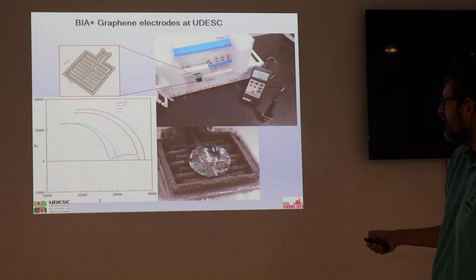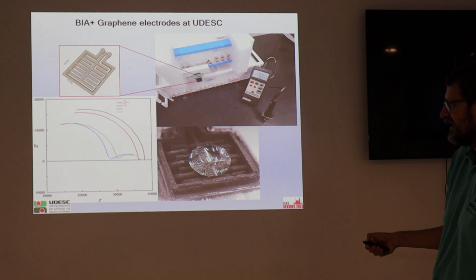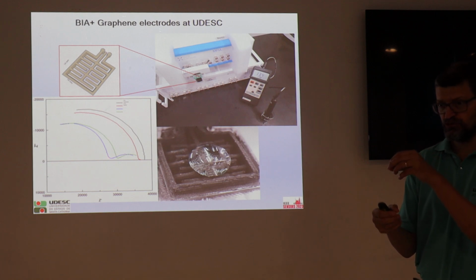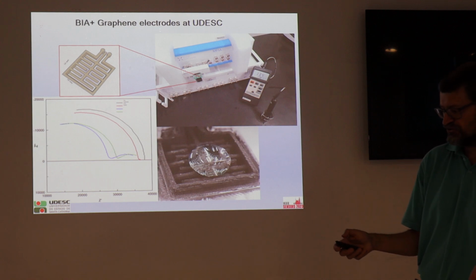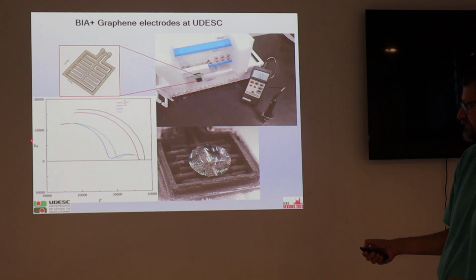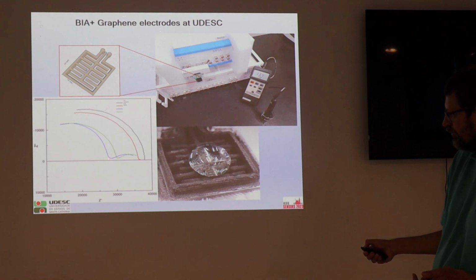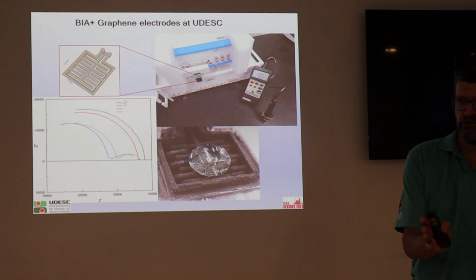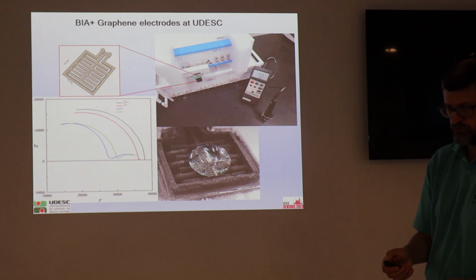Okay? And this is saline solution, this is an acid. So depending on the type of the solution we're putting there, the spectra change, therefore the real part and the imaginary part of the impedance change as well. Look, also the beginning of the increase changes, instead of here it is here, and this is frequency. So there's a shift in frequency that we can calculate as well.